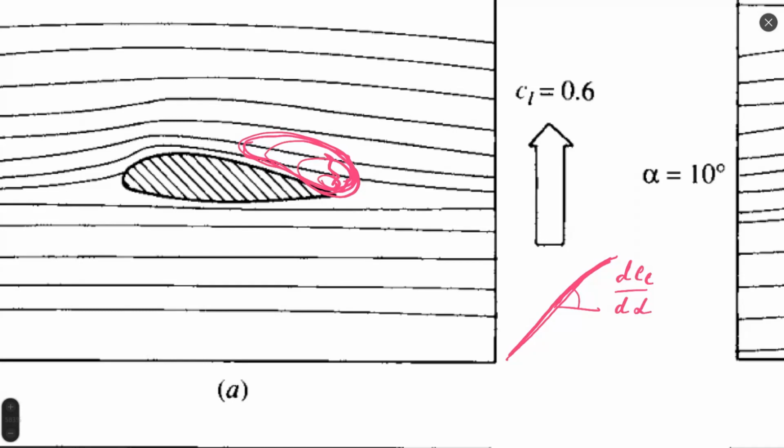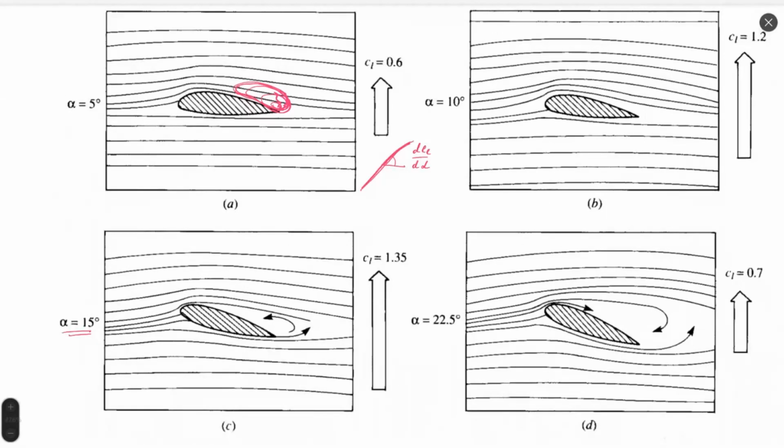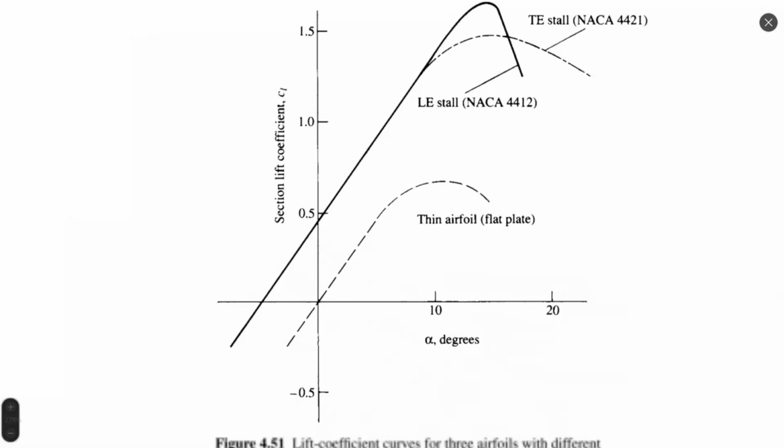So I think that lift coefficient growth is related not with existence of flow separation, but with the size or relative size of flow separation, how much flow separation occupies of total size of airfoil. Relation between area of flow separation and the total area of airfoil. Okay, I think it was clear.